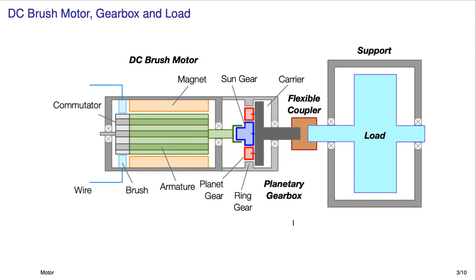That takes us to here, which is the business end of the motor. It's the output shaft of the motor. Oh, notice back here we have a little tiny shaft sticking out the back end, and that is useful for attaching encoders or other types of sensors. An encoder just measures the angle of the armature. Now this business end of the motor is attached to the planetary gearhead, which is here. Specifically, it's attached to the sun gear, and around the sun gear are some little planets. Now I've only shown 2 here, but in the motor that we tear down, you'll see 4.